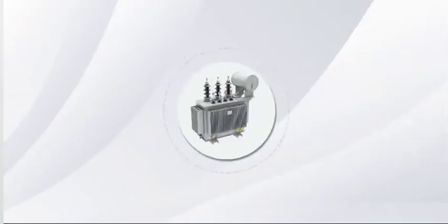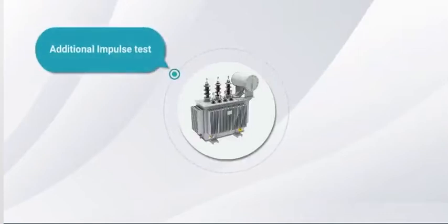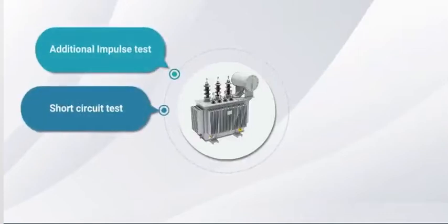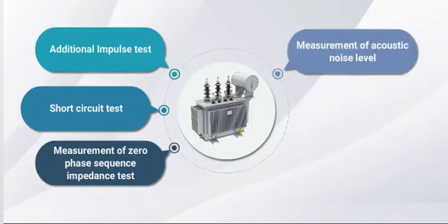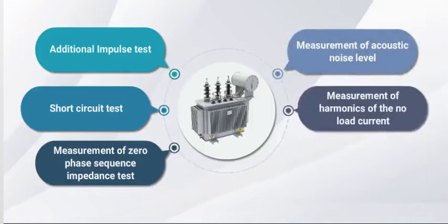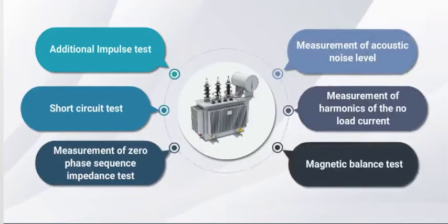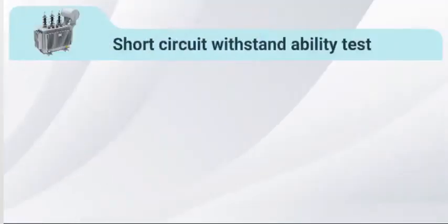Special tests can be categorized as follows: additional impulse test, short circuit test, measurement of zero-phase sequence impedance test, measurement of acoustic noise level, measurement of harmonics of the no-load current, magnetic balance test. Short circuit withstand ability test.